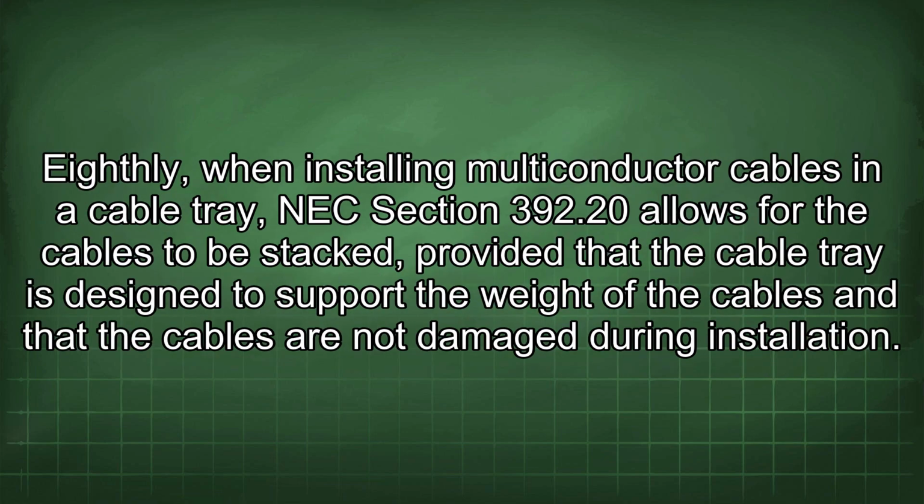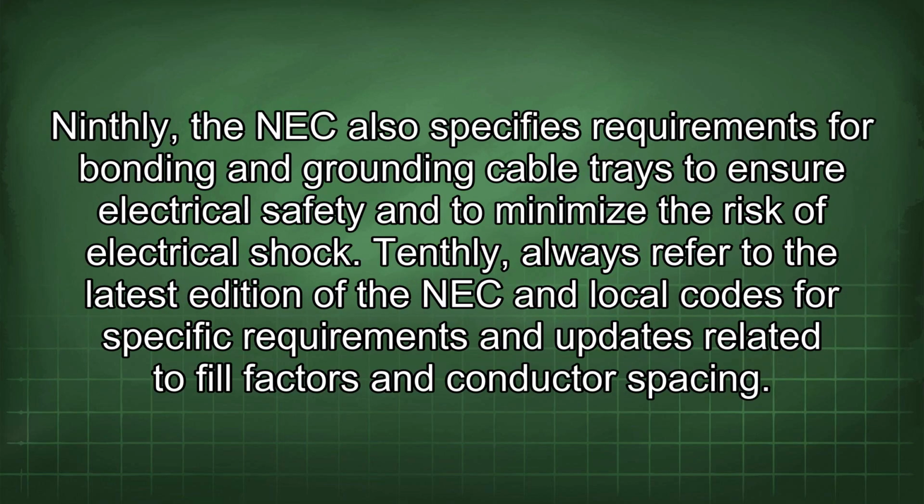Eighthly, when installing multi-conductor cables in a cable tray, NEC Section 392.20 allows for the cables to be stacked, provided that the cable tray is designed to support the weight of the cables and that the cables are not damaged during installation. Ninthly, the NEC also specifies requirements for bonding and grounding cable trays to ensure electrical safety and to minimize the risk of electrical shock.